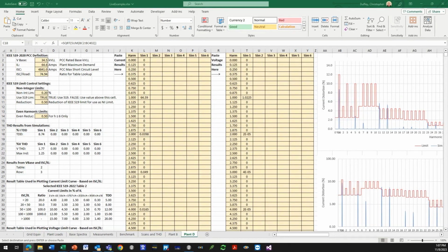Because let's say there's a lot of them, they can possibly accumulate, if you have many of these inverters tied in parallel or at different locations around the system, and they're accumulating. So yes, I would definitely model it. If it's on the AC side, then yes. If it's on the other side of the DC bus, no. But if it's on the AC side, absolutely, I would include it. But however, I would note,